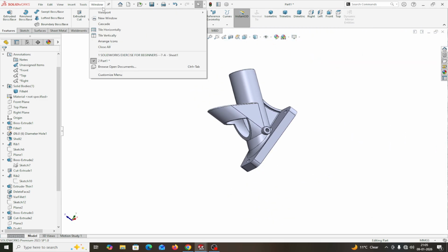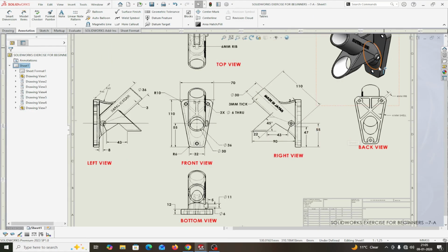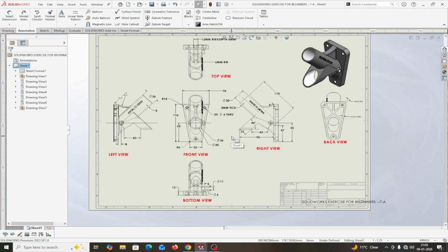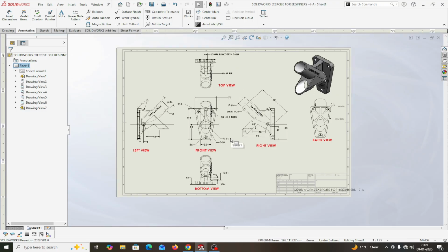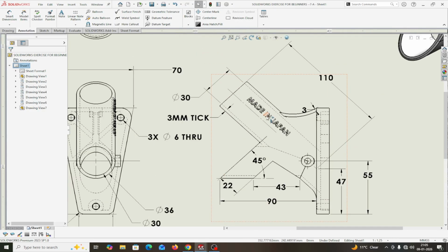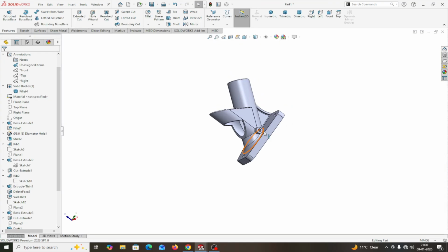In this way, if you see, I have provided all the things here. I made this bottom plate, this pipe, rib feature, all. In this exercise, we have learned the rib feature. One thing is left: you will see this embossing is taken. This is written "Made in Japan". And any text you want to write in the emboss, how can I write it?